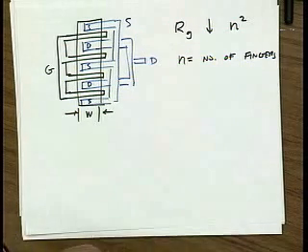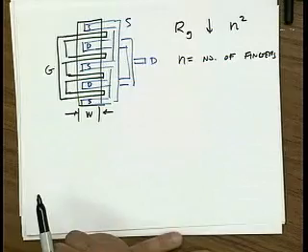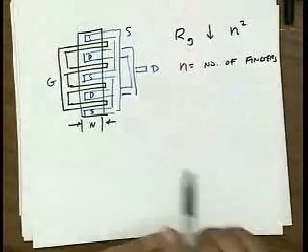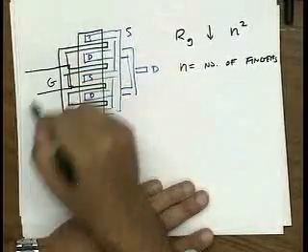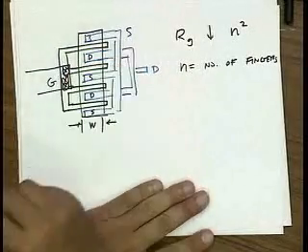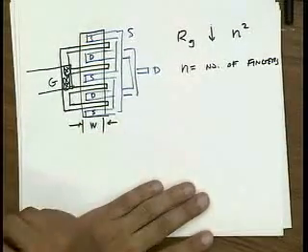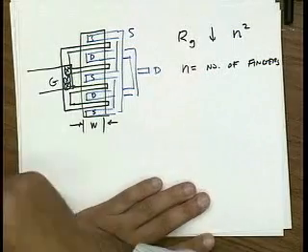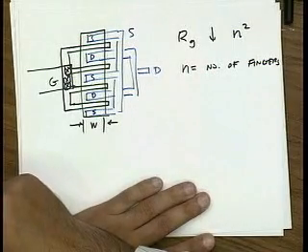Okay, you also bring up a good point about contact resistance. It turns out that when you lay out these transistors, you need to make contact to all these poly layers from top metal. So for instance, if I come in from top metal here and I have some contacts, then these contacts actually are quite resistive. They're tiny little plugs that might be 4 or 5 ohms per via.